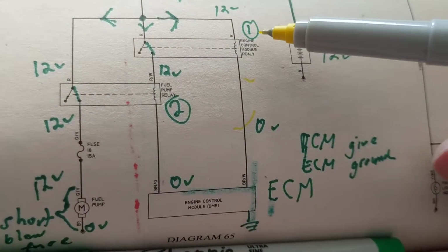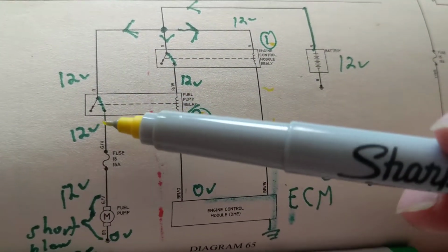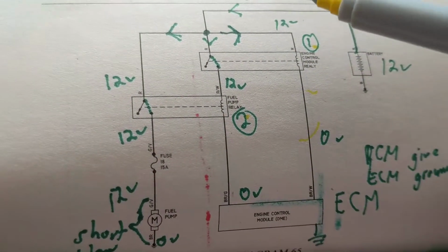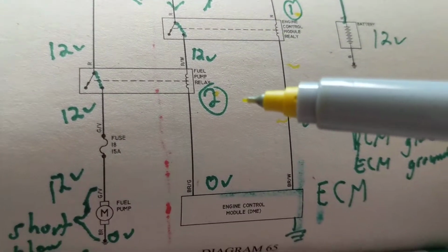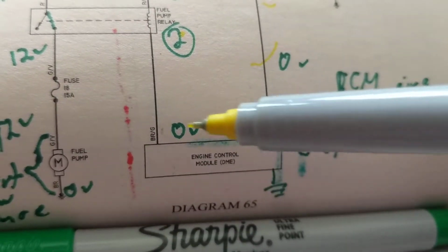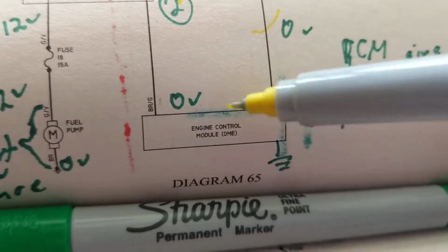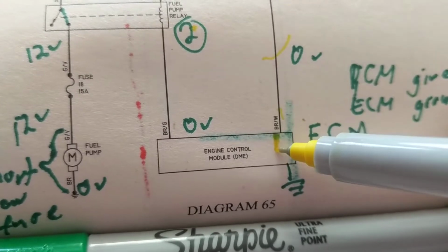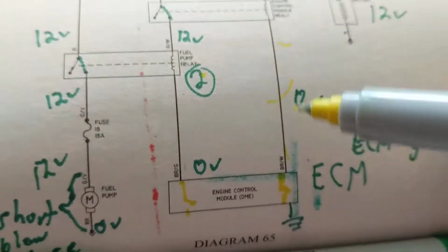I said, number one, for this has to happen, this has to happen, then this happens. But the most important thing is I need a ground. That's why I brought out the other diagram to show you. That control unit, if you remember, was a transistor. Here there is no transistor symbol. However, I know something has to give this a ground, so might as well give this a ground, a symbol of a switch.